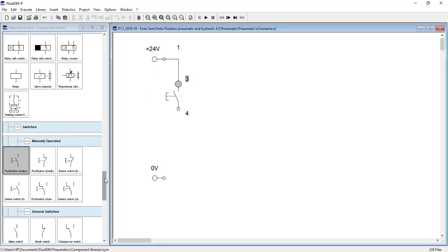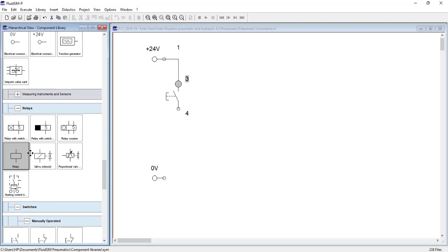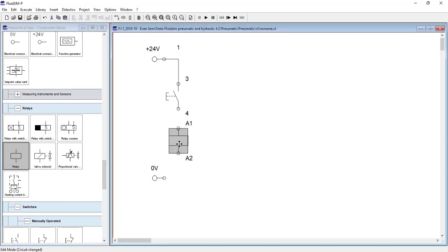With that, I am going to use a relay. So what are the three things of a relay? There is a relay coil, there is a relay NO, and there is a relay NC, right? It is not necessary that each and every coil's NO and NC has to be used. You can use either NO or NC, or you can use both. But definitely you need a coil.